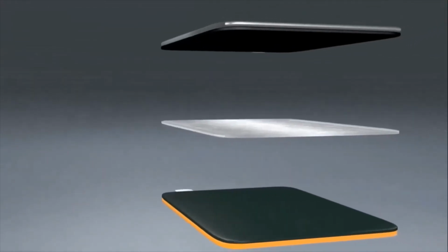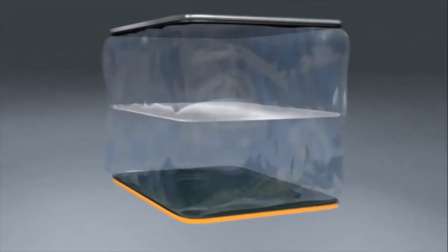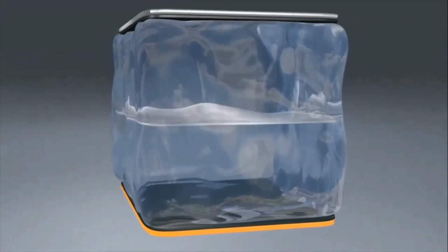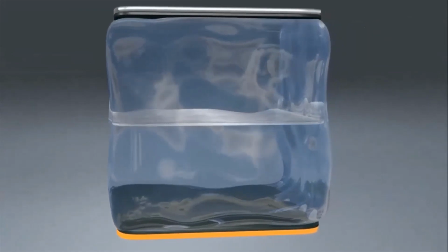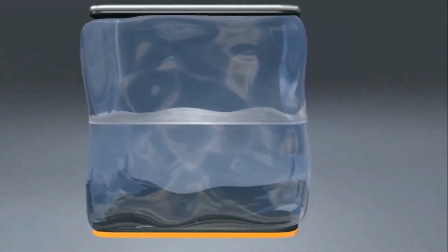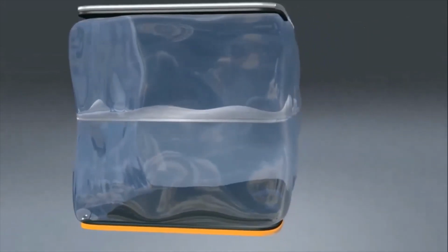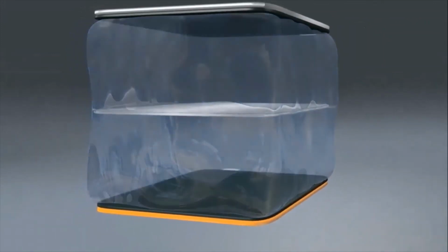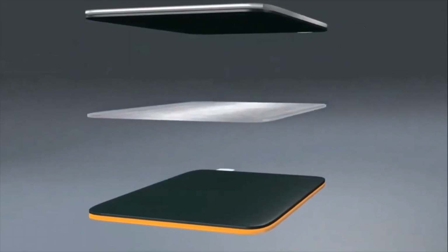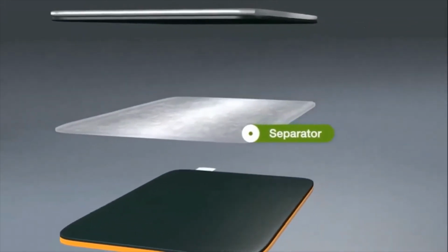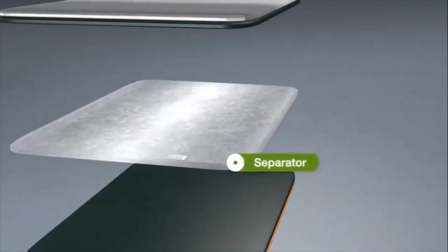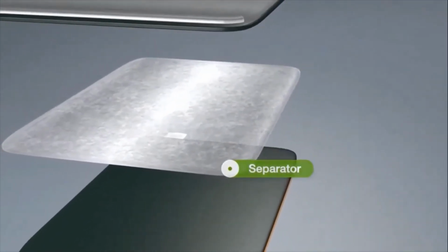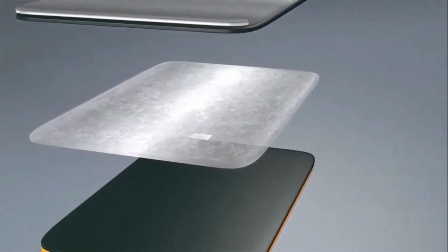The battery is filled with a transport medium, the electrolyte, so that the lithium ions carrying the battery's charge can flow freely. This electrolyte must be extremely pure and as free of water as possible in order to ensure efficient charging and discharging of the battery. To prevent a short circuit, there is an insulating layer placed between the two electrodes, the separator. To the tiny lithium ions, the separator is actually permeable. The experts call this property microporosity.